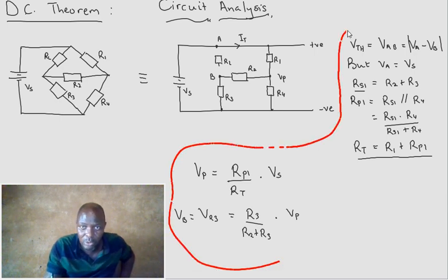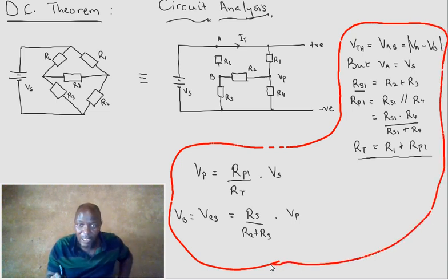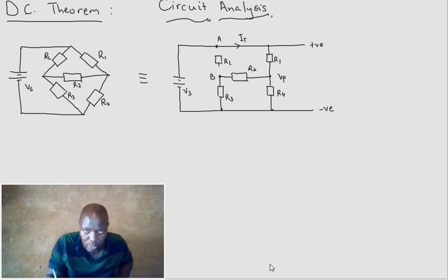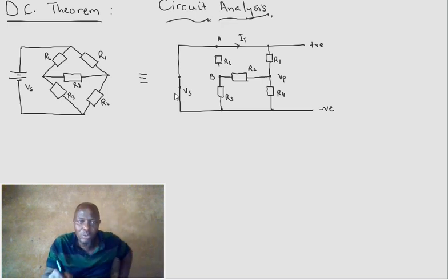This is a video, so people can stop whenever they want to. If I was a little bit fast, they can replay, and they can also go back and check if they didn't understand something. If we're to do the resistance, we simply replace the source with an equivalent resistance. If we are given a value, we put that value there. We're not given a value, so we put a wire. The resistance is 0. We assume 0 if we're not given an internal resistance.